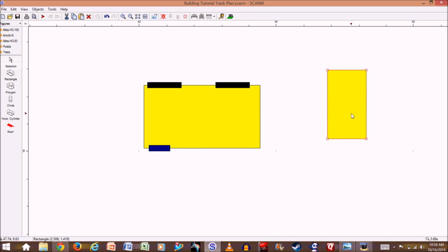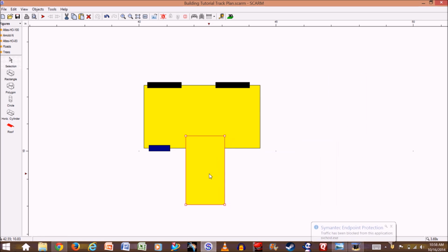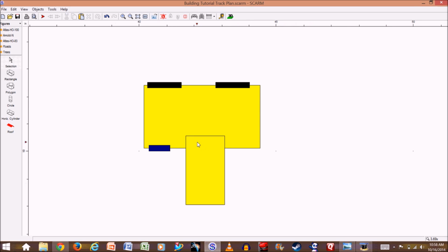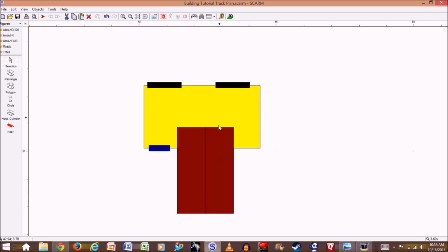Control, click to move, put it there, and then now when I select the object and put the roof on, now it will go vertical. Okay, so that's because I rotated the object. So if you want to make the roof exact dimensions so it fits perfectly on top of the square or cube, and you want the roof to be at a different angle, you have to first create your object horizontally and then rotate it, then put the roof on.